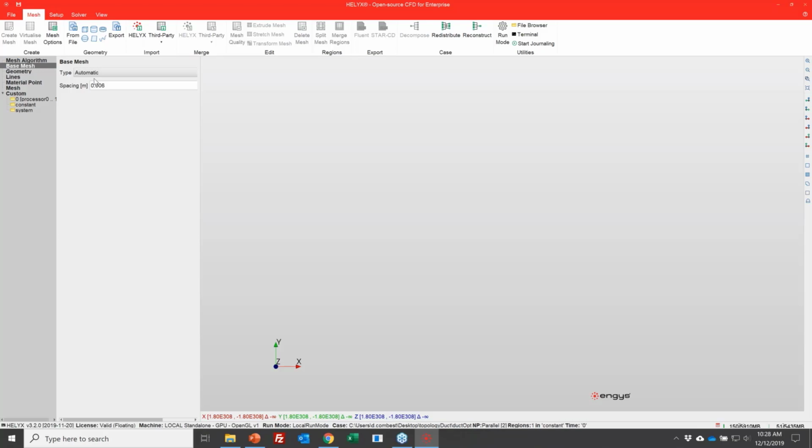And then where these surfaces that I'm about to import intersect, it will refine according to how I tell the mesher, and then remove the cells outside of the particular zone that the simulation will be carried out in, and then it'll do some smoothing and we'll have a final result. So that's the big picture of how the mesher works. So let's go to geometry.